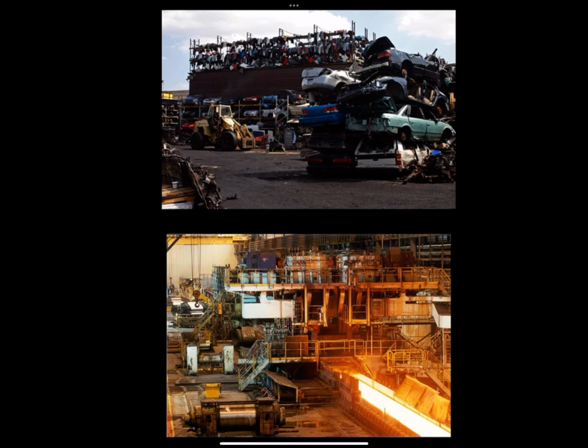So using recycled steel requires less fossil fuel, less heat, less water, and this reduces the embodied energy of steel significantly. Also on the plus side, steel gives better performance per pound than concrete. Steel is lighter in weight than concrete for the same job. So if we have to span 30 feet, we can do it with a steel beam, which will weigh less than a concrete beam for the same span.